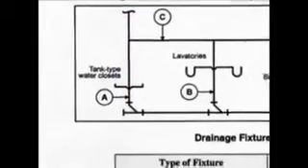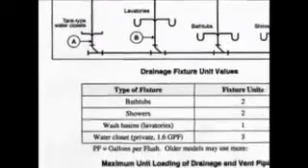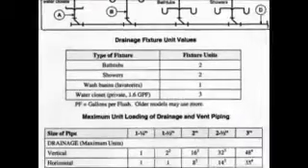So we look at drainage fixture unit values. We're trying to figure out what the unit values are. We come down the list. A fourth in the list there under type of fixture is water closet. Private, 1.6 gallons per flush. That is 3 fixture units per installation.